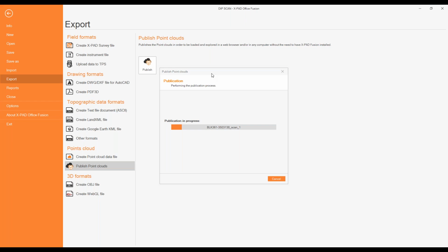If you have other point clouds that you want to share with the customer, you can use the main point cloud format, E57 or LAS, which you can generally open in all the main CAD software that can manage point clouds, from AutoCAD to Revit, Edificius, and all the other software available on the market.